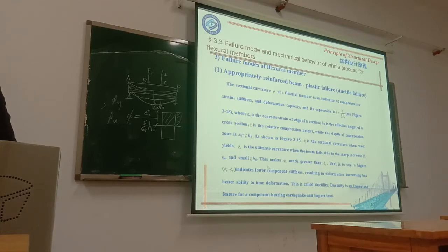A high value of phi u minus phi y indicates lower component stiffness, resulting in deformation increase, but better ability to bear deformation. This is called ductility. Ductility is an important factor for components bearing earthquake and impact force load.